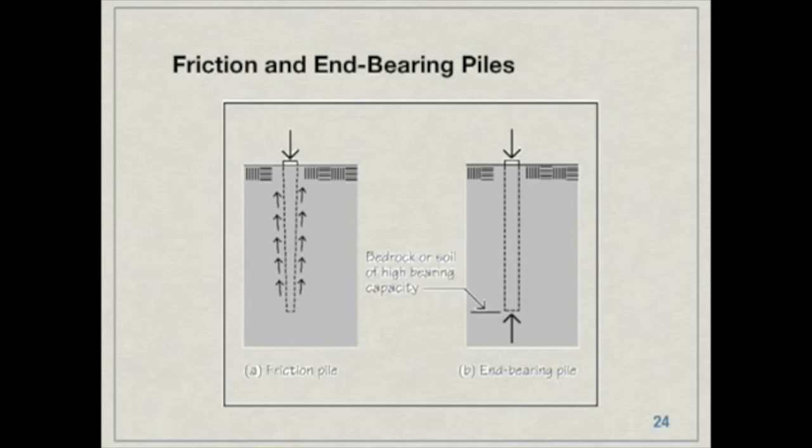Now again, piles can consist of either steel, it can be made of reinforced concrete, pre-stressed concrete, or wood. Now wood is typically used only where the loads are going to be lighter for a number of reasons. Obviously it's not as strong as steel or concrete, but also wood piles come from tree trunks, and tree trunks just only get to so much of a diameter, whereas steel and concrete we can fabricate to any size we wish.